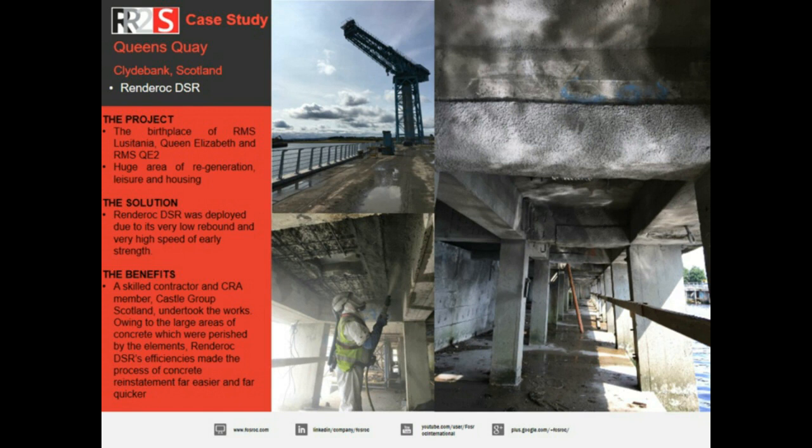The fact that it was rapid set came into its own in 2 different ways. It's a tidal area, so if you're placing concrete to that scale, if you're in a tidal zone, then that has a knock-on effect on how much work you can get done in the setting time, if you like. So the fact that this is setting within 15 minutes and would allow a tidal wash to come over it, that speaks for itself.